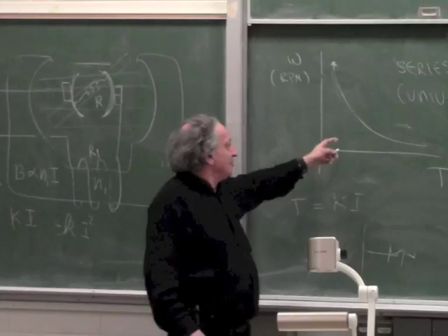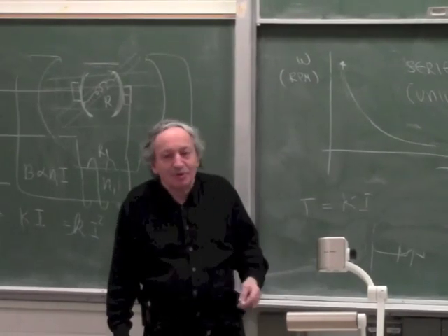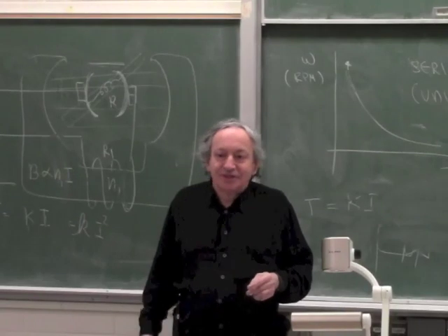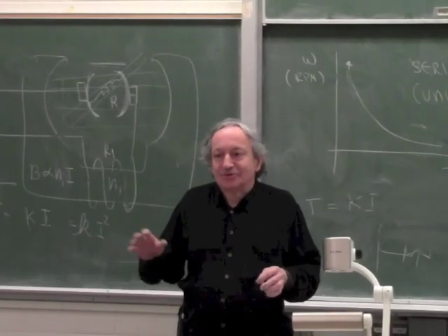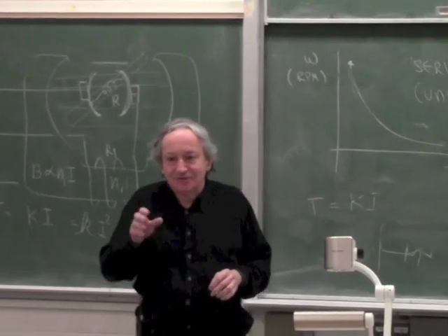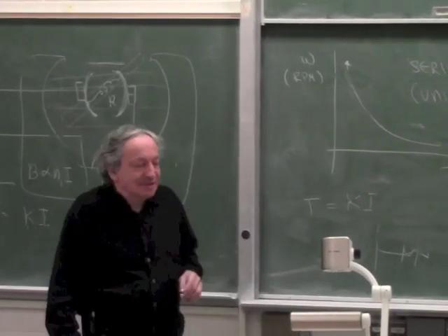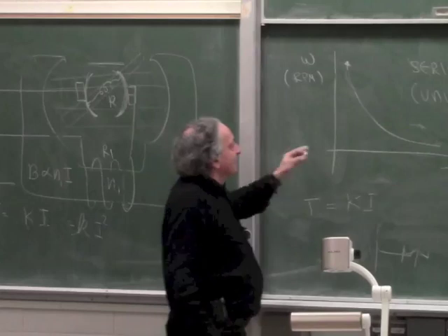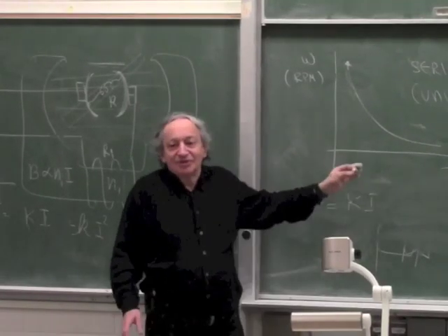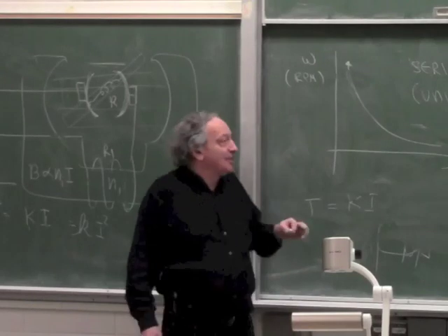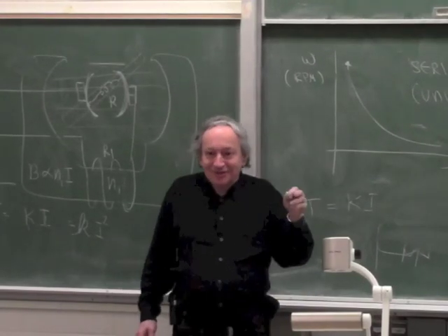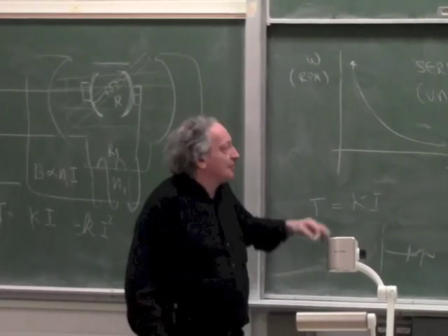But if you have a DC motor, that's why these motors were very popular in early electric cars. Today they're using synchronous motors or induction motors for other reasons, mainly of commutation. They don't want the sparks. But if you made a simple electric car, like a golf cart, this was an ideal motor because it always gives you the maximum power. But you have to be careful because you don't want the car to run at infinite speed if there's no load, like downhill. So you have to limit it.